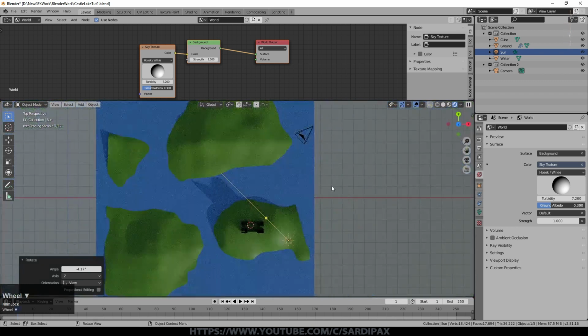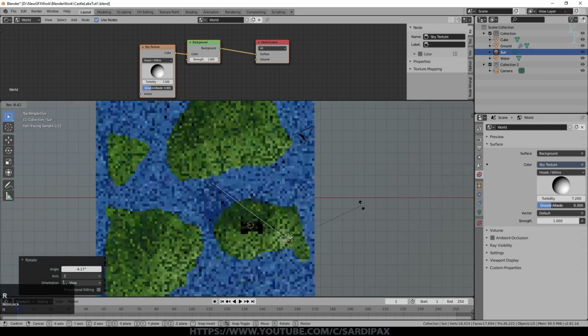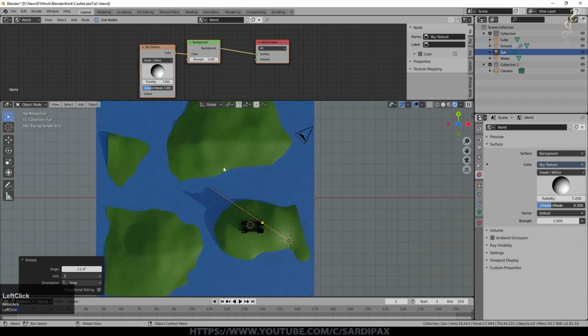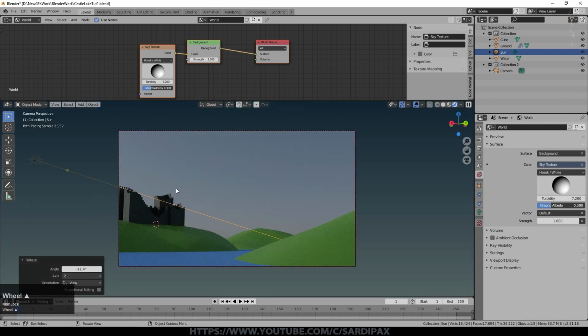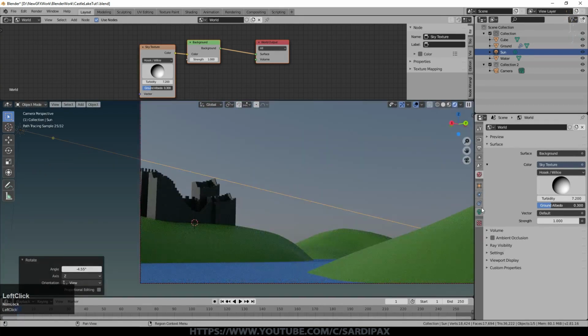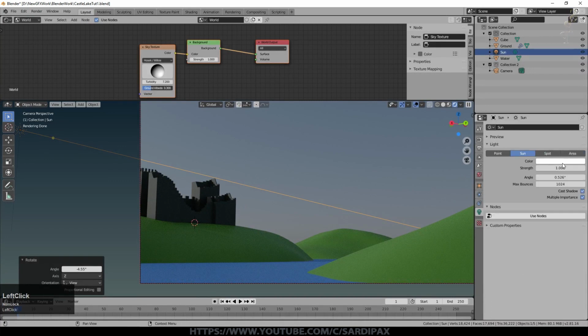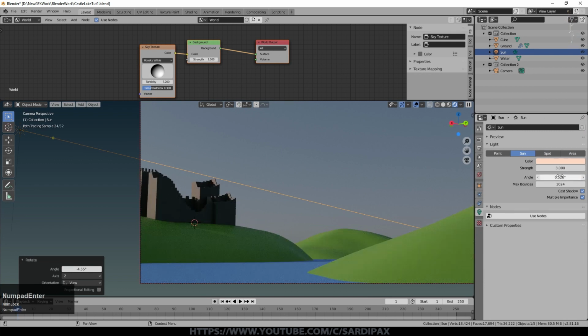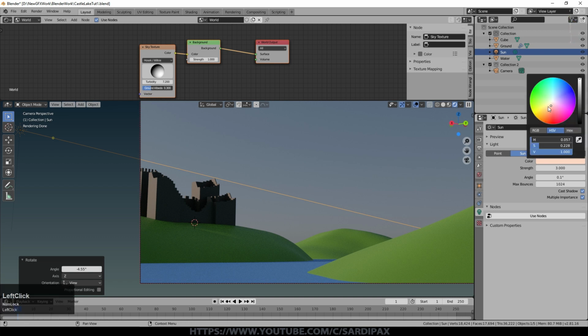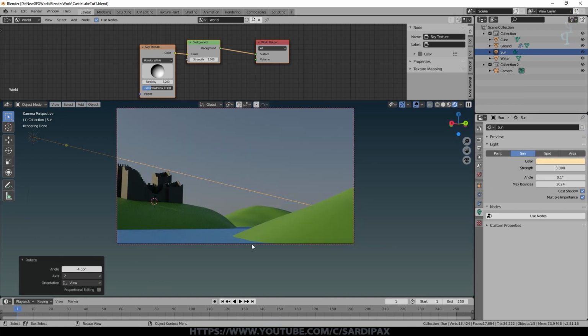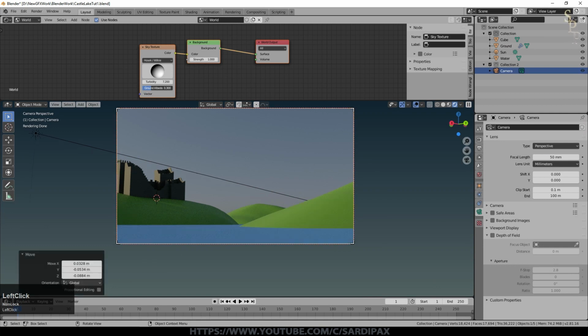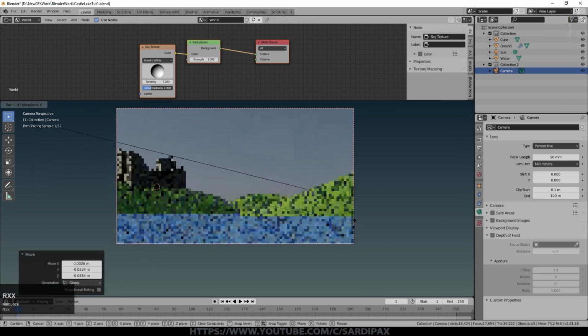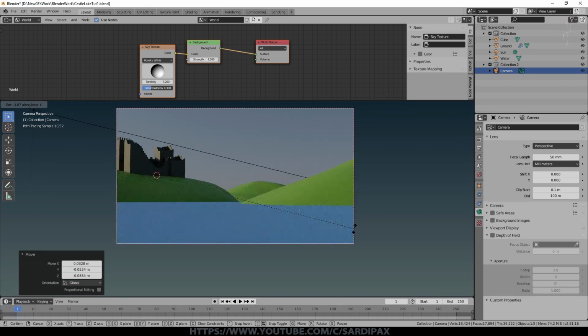And in terms of the camera, because I want it shining across it somewhat, let's bring that round a little bit so you can see where the shadow of things are. No point in me pointing at the screen. And then we'll go to our sun lamp settings, give it a fairly yellow orange colour. We'll set it to 3, and we'll give it at the moment quite a small angle, so it's a relatively clear sky. We may change that later and give it more colour than that. Okay, so I think we just need to rotate X on our camera just so that we get a little bit more water in it.